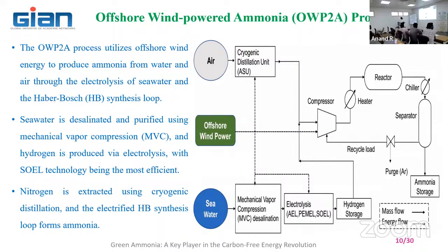As the question was posted, why don't you use the seawater for producing the hydrogen? This is the answer. Seawater contains minerals and salt, which can corrode the components. To avoid that, you can extract the water through a solar desalination plant. You provide heat in the form of solar radiation. Due to evaporation, the saline water remains at the bottom, and the drinkable water, due to its low density, comes out. It is then used as water for producing hydrogen through electrolysis.